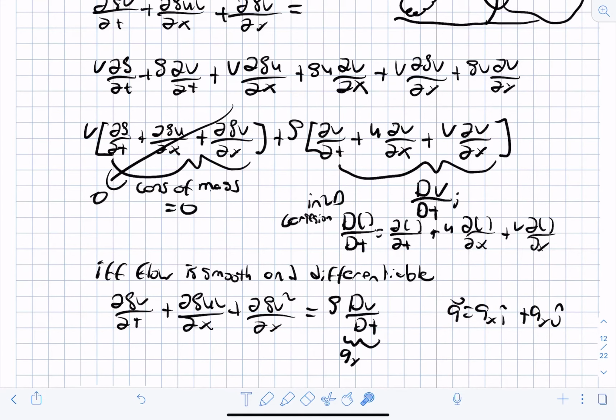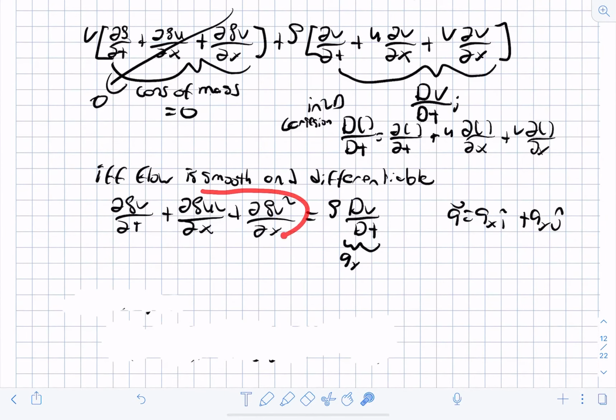So really this is nothing more than mass times acceleration in terms of Newton's second law. Then we can replace this in the Navier Stokes equations with density times the substantial derivative. We can do the exact same thing for the x component, and we'll get the same result, except that it will be rho Du Dt, not rho Dv Dt.